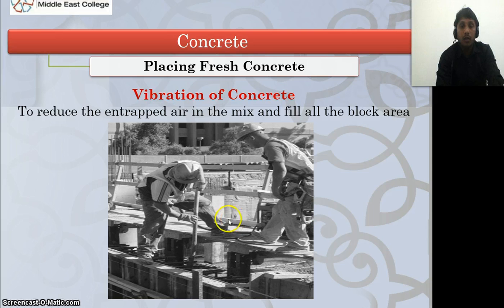Vibration of concrete. It is very important to vibrate concrete, because there may be a lot of voids when the concrete is placed. But once it is vibrated, all the air gaps and voids in the concrete will go out, and the concrete settles without voids and without any permeable spaces, so that this helps in gaining the strength of concrete.